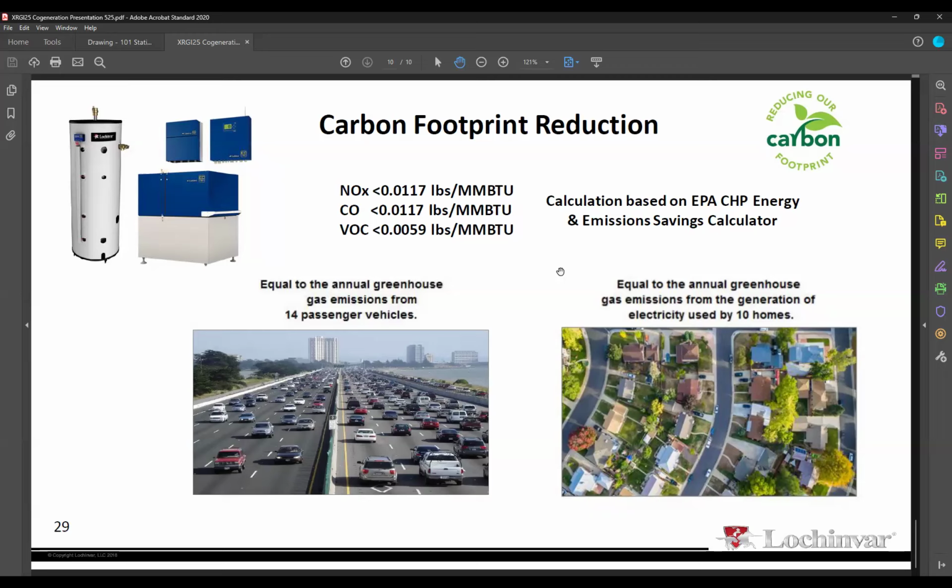But you will hear some people saying they have an instantaneous unit, and the reason is kind of funny and deceiving. There's a couple of companies out there that use the heat pump to heat up a glycol in storage tanks, and then they have a reverse indirect coil, so the domestic water is instantaneously heated.